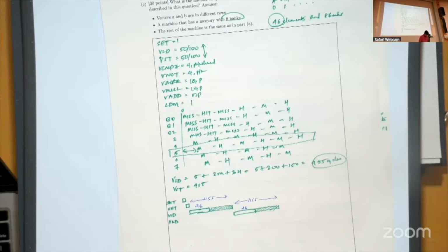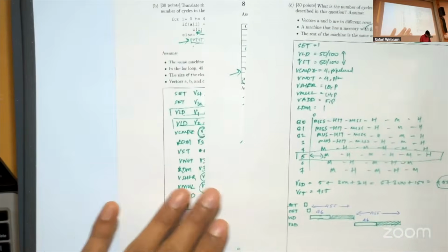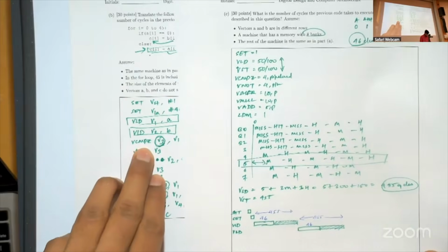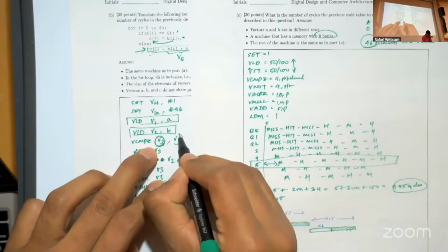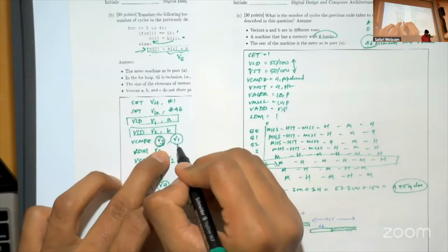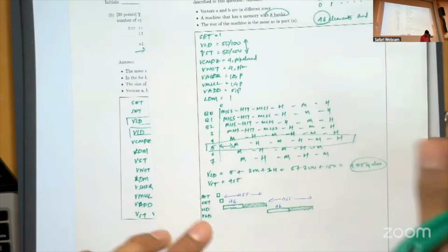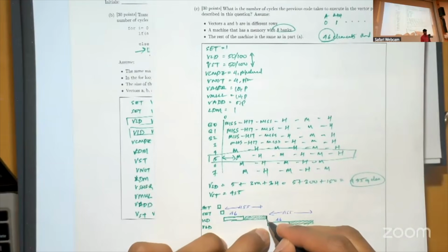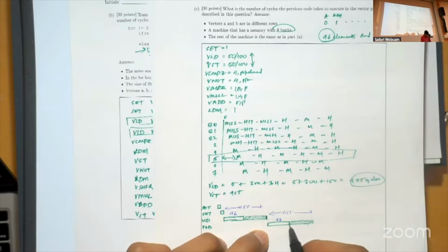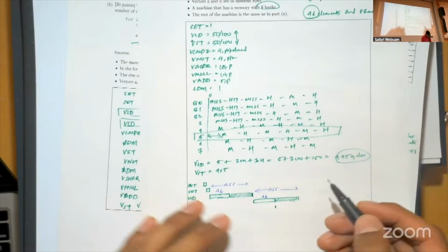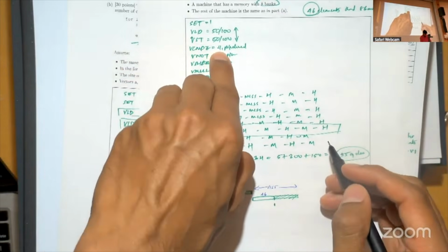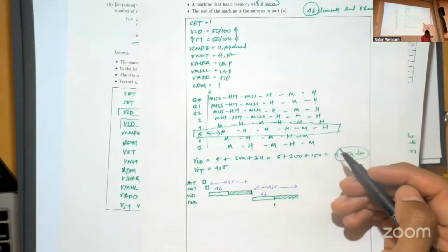And after the VLD instruction, you have the vCompare to 0 instruction, which relies on one input, V1. And the data for V1 is available already at this point. So after the 46 cycles have been spent, you can start the vCompare instruction.